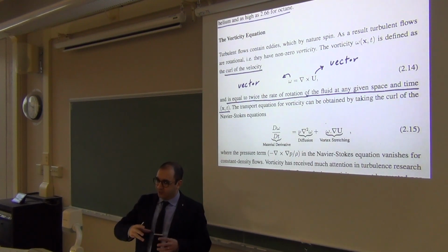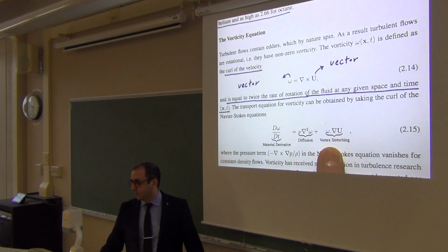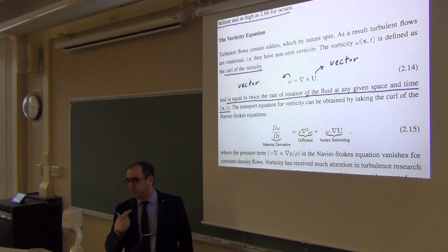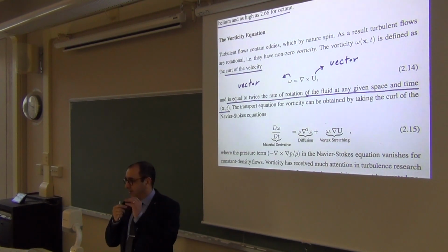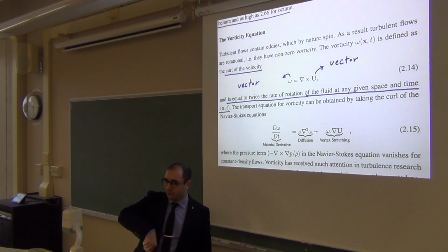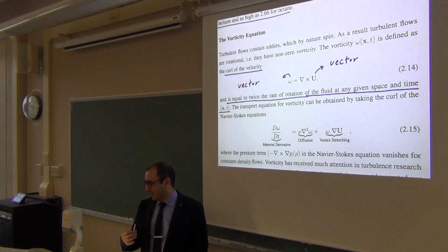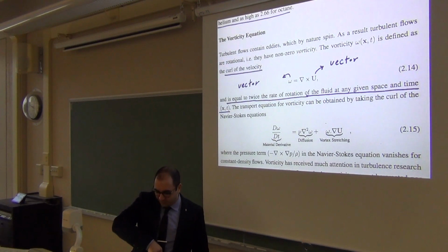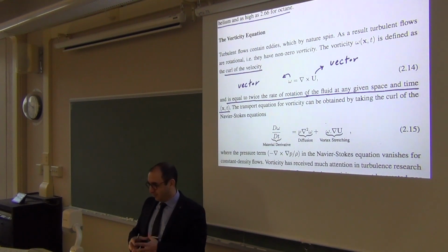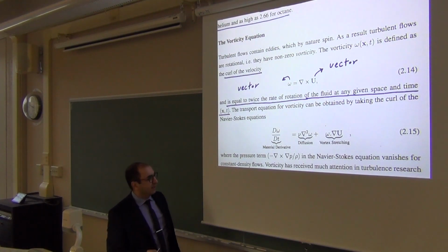This spinning motion can stretch in different ways depending on what the flow is doing around it. Especially if you put a blob of spinning fluid in a field of flow, it will be stretched. I mean, if you go swimming, you can try these things. Have you seen people start a vortex in a swimming pool and watch it move around? It's that kind of stuff. You can start one and then put it in front of flow. It will be stretched. Eventually it will diffuse. But it's really fun to think of it as an independent property.